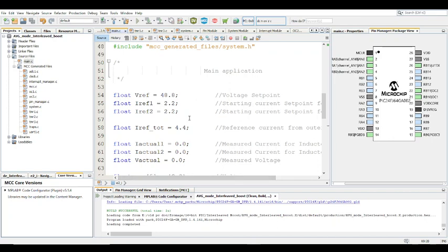So that's basically average current mode control for an interleaved boost converter. Interleaved topologies are really good in terms of sharing the current load. They have higher efficiency because you're essentially halving the amount of the parasitic resistance that the current has to go through. You're sharing the current through two inductors, so the resistance that has to go through is less, and in essence you have a higher efficiency. So interleaved topologies are really good. Great advancement in power electronics. Whoever came up with it, I actually don't know, but it's really good.